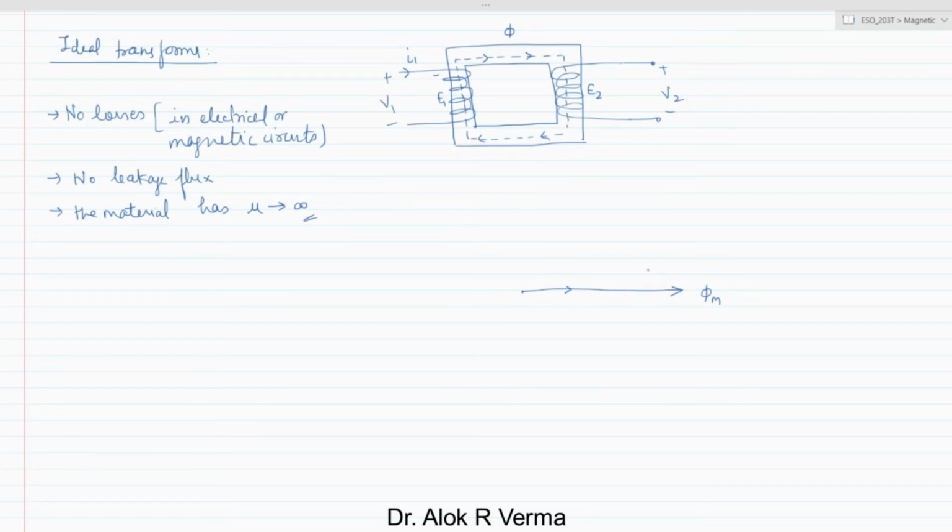So this is Im or I mu, the magnetizing current, and the voltage induced in the core, E1, lags by 90 degrees. We have seen this in the EMF equation. E1 and V1 will be opposite due to Lenz's law, and E1 is equal to E2 and V2.